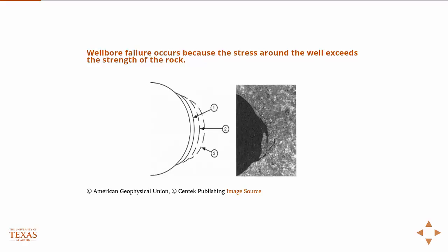and so the actual stress, the full state of stress, the stress tensor, is what really matters, because when we design well bores, especially in deviated wells and other things, if we don't have the correct state of stress or hoop stress along the well bore, then we can get tensile failures or other types of failures, and then you have an unstable well bore. Okay, so this is one aspect of why we care about stress as petroleum engineers.